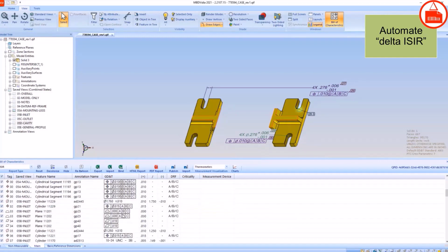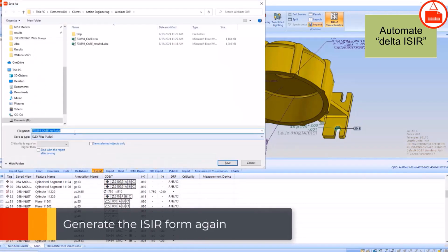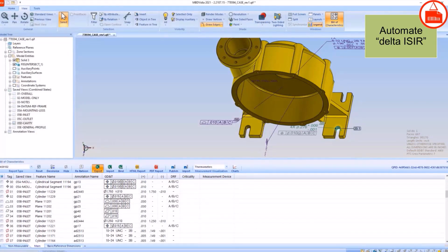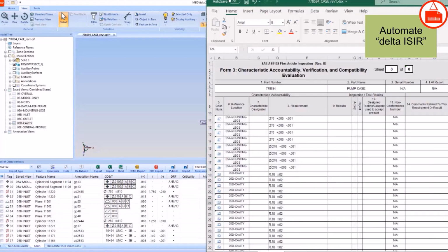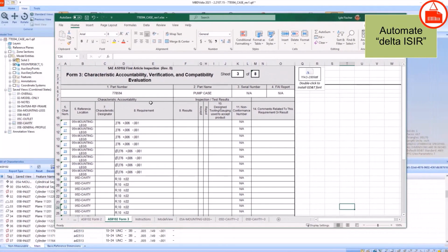So this is a pretty typical process. But again, looking at today's typical 2D drawing-based approach for how to do this, this is a very time-intensive process. Basically, someone just needs to go through the drawing for each of the two revisions and figure out manually what's changed. But really, that data should exist on the MBD, and you should simply reuse that data. So really, none of that extra work should be necessary. It's all a natural part of an MBD workflow.